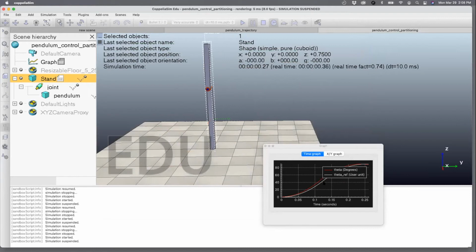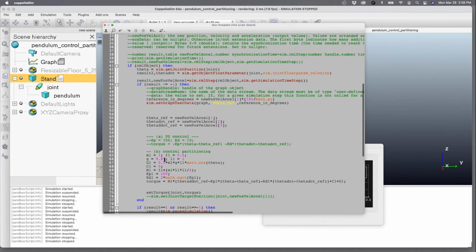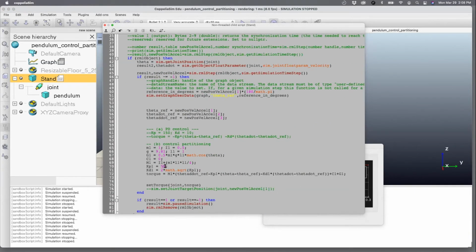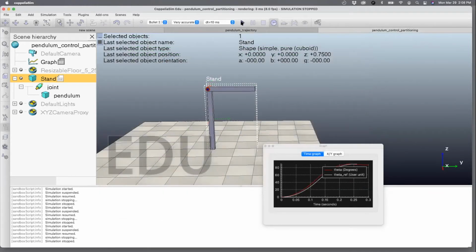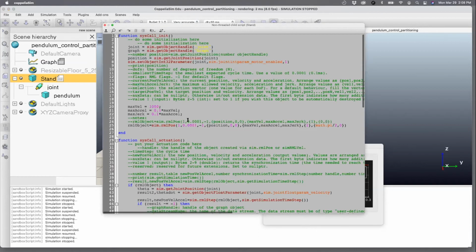That's good. There's some problem here. So there's some point of time, the integrator will actually affect your results. So you can't just ramp it up. It's like 50. Yeah, that's pretty good. There's still an error. So that's like, if you're trying to go 90 degrees in 0.25 seconds, that's a really fast control. So yeah, this works, I guess, better than naive PD control.